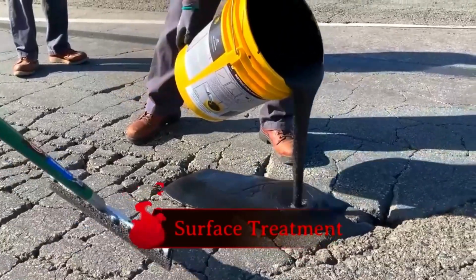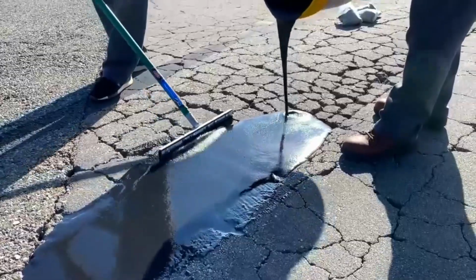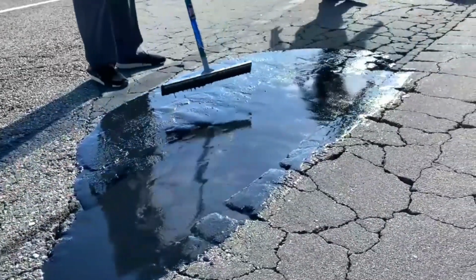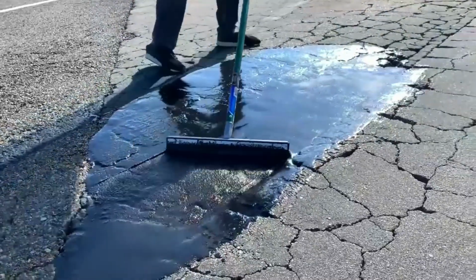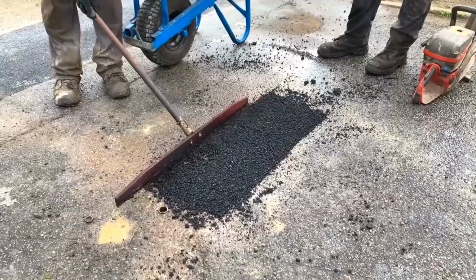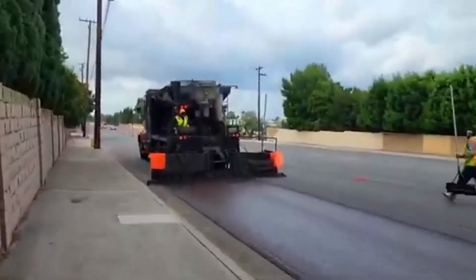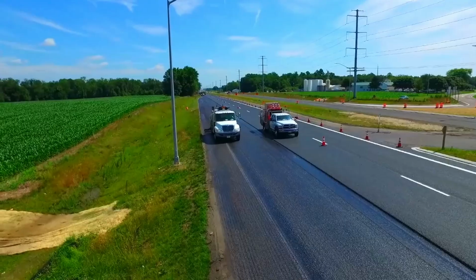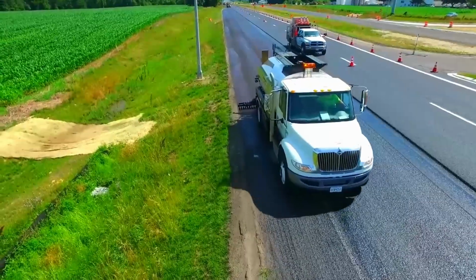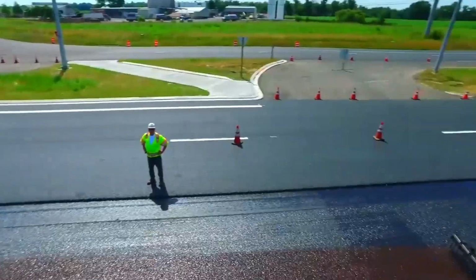Step 3. Pre-overlay surface treatment. To ensure a strong bond between the old pavement and the new overlay, additional treatments are applied. Crack filling. Large cracks are sealed to prevent reflection cracks in the new layer. Pothole patching. Deep potholes and ruts are repaired before overlaying. Leveling course. A thin layer of asphalt is used to correct surface irregularities. Tack coat application. A bonding agent is sprayed to improve adhesion between layers. Proper surface treatment ensures the overlay lasts longer without premature failure.